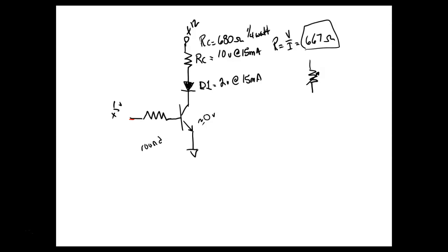Since this is only 15 milliamps, we're going to use a 2N3904. So we've chosen a transistor. We have tons of those, so you can see why I chose a 2N3904. That's the 3906, this is the 3904. We got plenty of them. I'd look at the data sheets, and I'd make sure the collector current can handle it when it's saturated. I think this thing is rated at like 600 milliamps, so we're well within the limit.